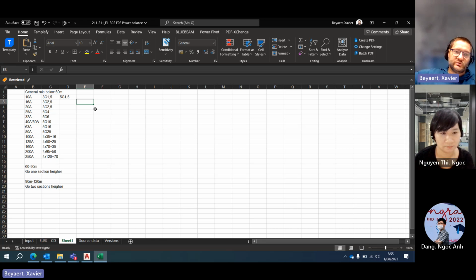So all the consumption also has a part in the voltage drop. If you would take 16 amps at the end of the circuit at 60 meters, you will have a problem. But if you only take 1 amp at 60 meters, you don't have a problem. That's the idea behind it and the technical explanation.